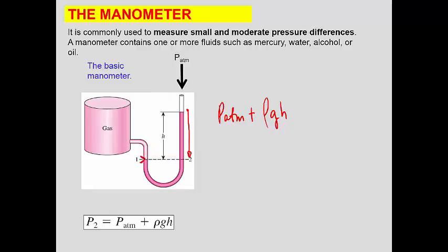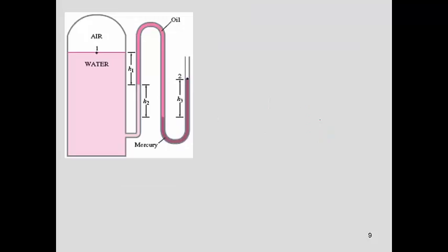And then here you have the P gas, and it's a gas, so the pressure is all the same. So this would be the pressure that the gas exerts. Now, reviewing the same concept, let's go from point 1 to point 2 to calculate either P1 or P2. So I have P1, and now I'm going down here. So I say, okay, times the specific weight of the water times H1.